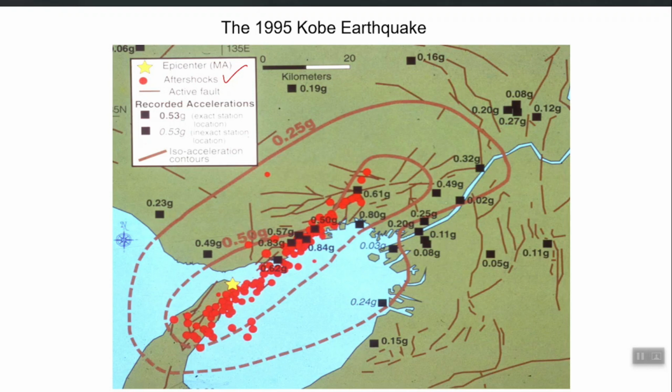But overall, if you have enough points, you will see that as you go away from the seismic source or fault, the recorded PGA value will reduce, right? The relationship between these two things is called the attenuation model. This is an important component of PSHA, which I explained maybe in the first session also. Let's say this is the fault line, and all the black dots are the PGA values recorded at different distances.